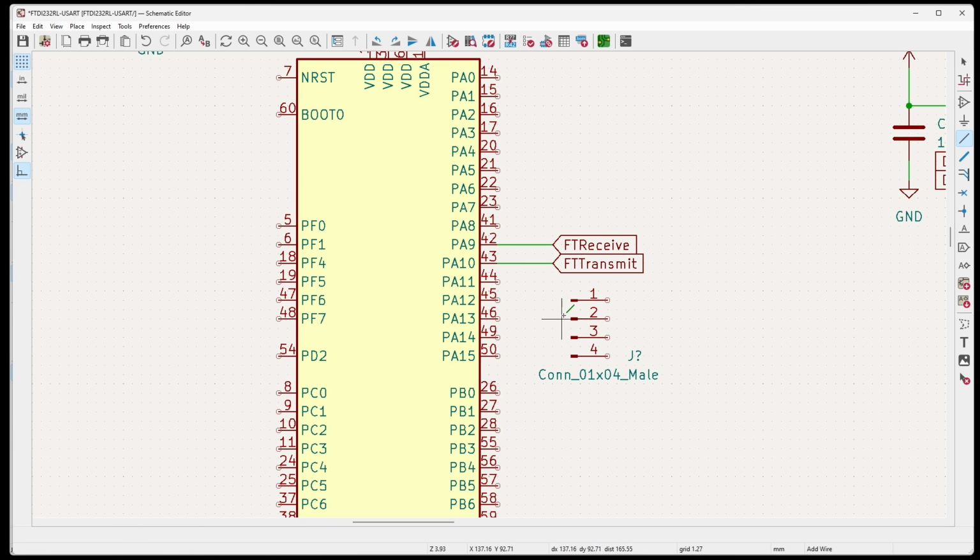The next thing I need to figure out is which pin should I have going to the 13 and 14. It doesn't really matter because the SWCLK and the SWDIO and the 3.3 volts and the ground, they're all individual pins. So I can pretty much make it any one I want, but I do want to make sure that it is labeled on the PCB. Oh, this is in the wrong direction, so let's rotate this around.